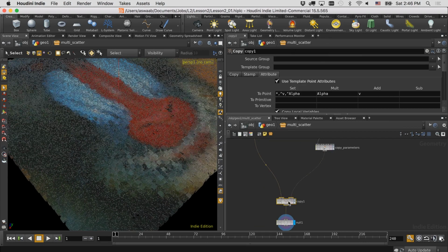So you can see the way that this copy SOP works. When we choose this, it's going to want to know which attributes am I copying to the point. What this means is the star means copy everything. And then we have a comma here, and then there's this little hat kind of symbol, I forget what the official name for this thing is. But that means except, like don't do this. So just saying, give me everything except velocity.